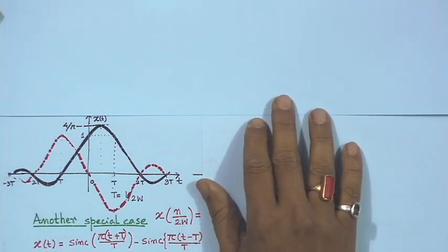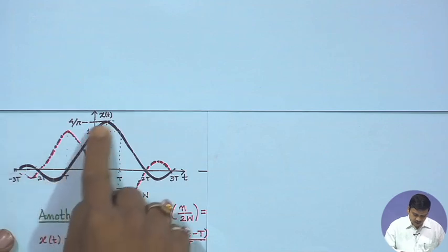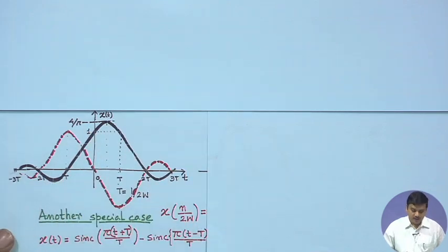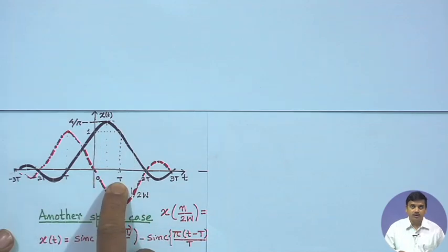for which we introduced the kind of signaling techniques known as partial response signaling, and we are introducing the pulse shapes or the signaling scheme known as duobinary signals. So, we explained briefly how the pulse shape would be. The pulse shape that we have is the solid one over here, which has non-zero values at 2 sampling instants.